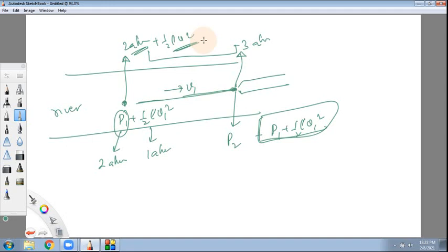So the stagnation point is very important. When you have an obstacle, very near to the obstacle there will be a stagnation point where the fluid comes to rest. If you use Bernoulli, because it came to rest, there the pressure will be quite huge, because the half rho v square term is becoming 0 there. So the other part of Bernoulli's equation, the pressure, becomes quite huge there. This is the idea. This is something which was not there, and I'll add it to our video series.